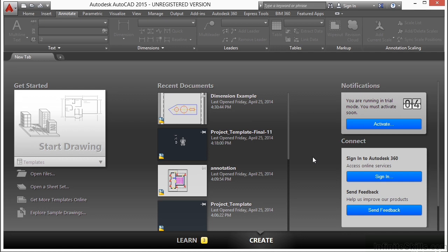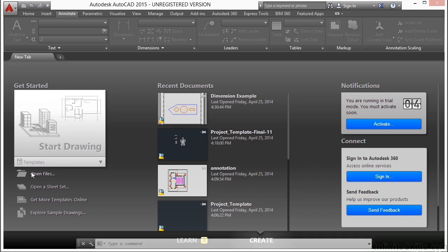You can use those viewports to arrange the views of your drawing on a sheet. You can move and resize layout viewports all that you want. By using layout viewports, you have more control over the display. For example, you can freeze certain layers in one layout viewport without affecting the others. Let's open up the ice rink example file.